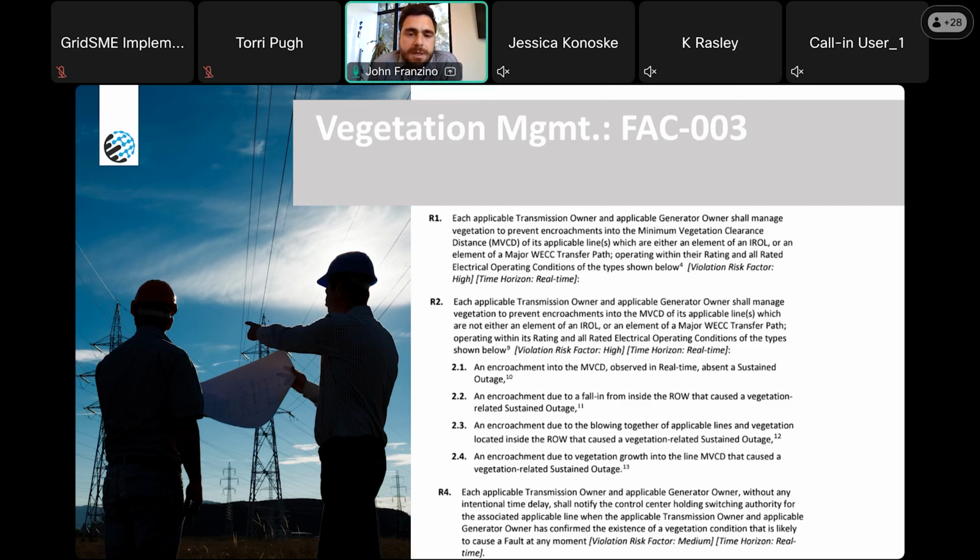The answer is yes. That program obviously doesn't maybe result in vegetation maintenance because there is no vegetation to trim and prune. However, you still need the program to periodically inspect and ensure that vegetation will not encroach your right of way and risk contacting the conductors on the gen tie.